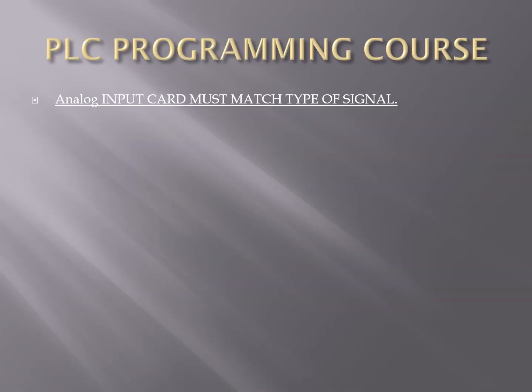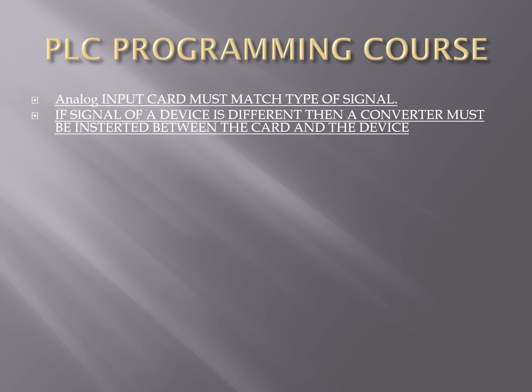An analog input card must match the type of signal on the device that is attached to the card. If the signal of a device is different, then a converter must be inserted between the card and the device.